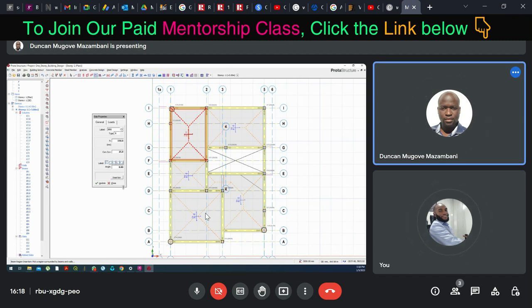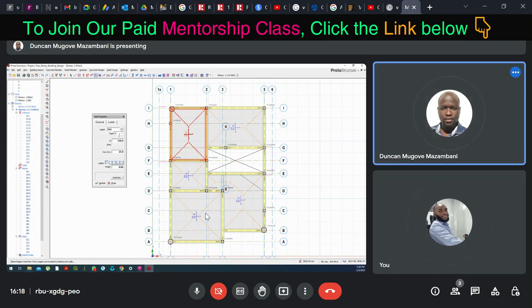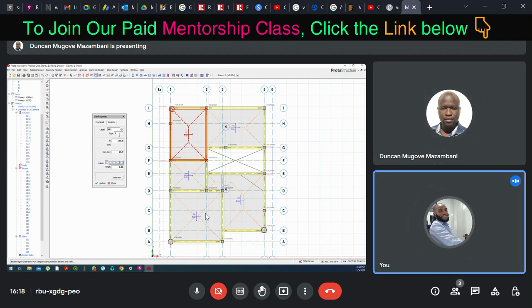you see type. Under label, before the depth of the slab, there's type 1. So now click that place. To put a cantilever slab, you need to choose type 12. Type 12 is for cantilever slab, while type 1 is just for a normal slab. So choose type 12 for a cantilever slab.